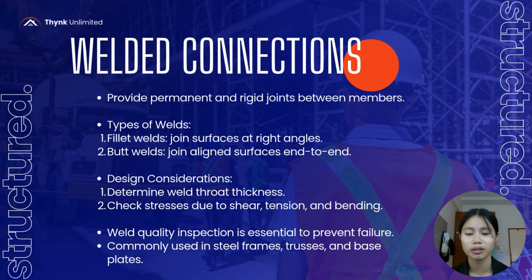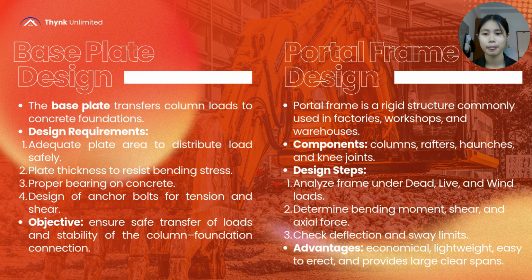And then design considerations. First, determine the weld throat thickness. Second is check stresses due to shear, tension, and bending. And then weld quality inspection is essential to prevent failure. And lastly, it is commonly used in steel frames, trusses, and base plates.